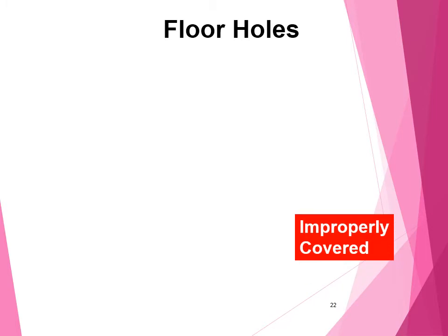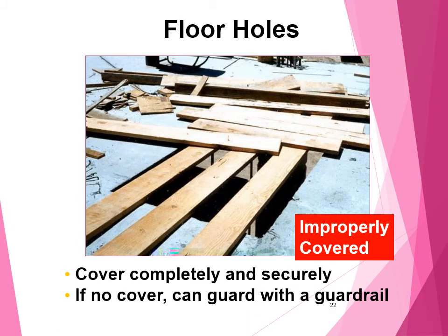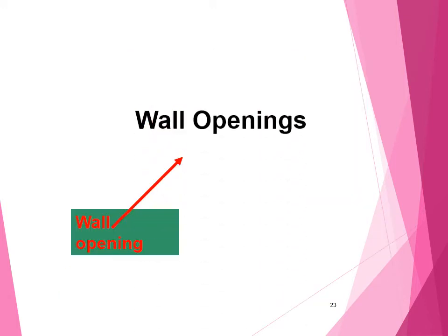Floor holes. These floor holes have been improperly covered. When you are standing on the planks, you might fall down. Cover completely and securely. If there is no cover, guard it with handrails.